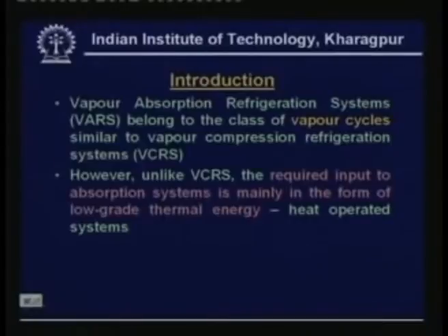What is the difference? Unlike vapor compression refrigeration systems, the required input to absorption systems is mainly in the form of low grade thermal energy. If you remember, in the compression systems the major input to the system is in the form of mechanical energy to run the compressor.